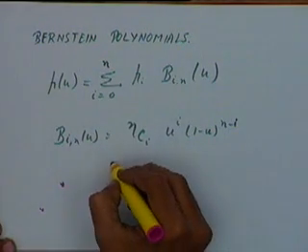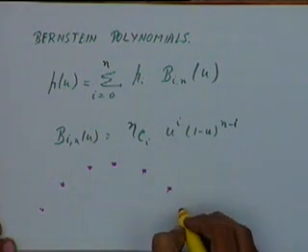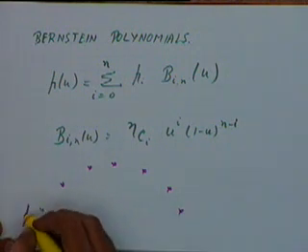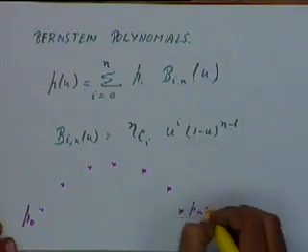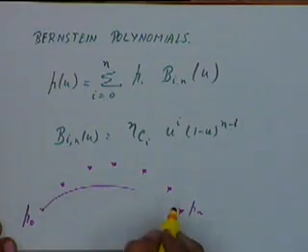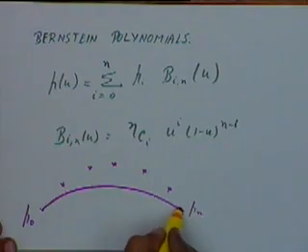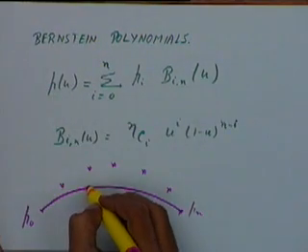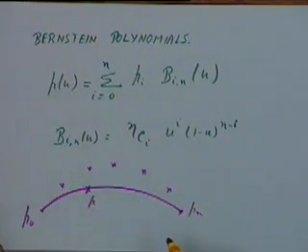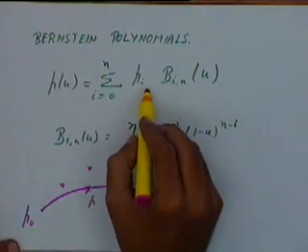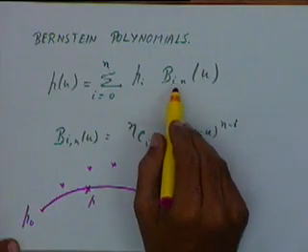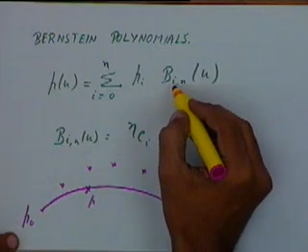So if you have a set of control points like this, this is my point P0, this is my point Pn, and we get a curve between these points like this. What we are basically saying is that the coordinates of any point P are given by the sum of the Pi into Bi,n terms, where Bi,n is the weightage given to the point i.